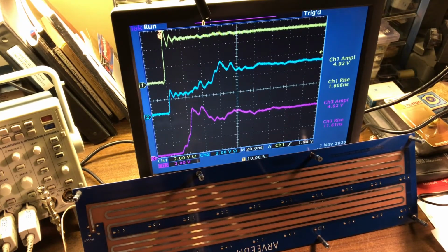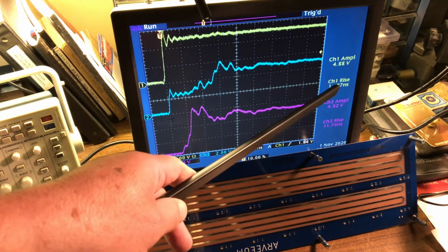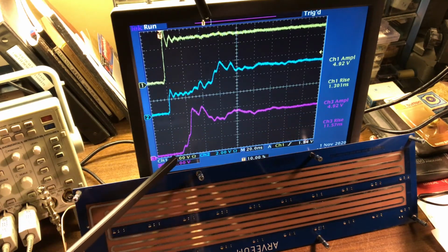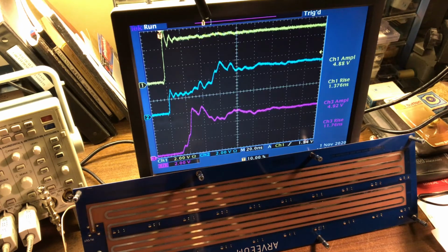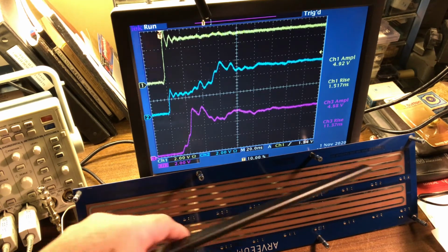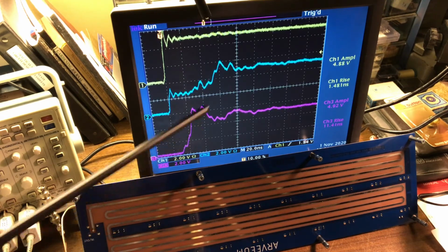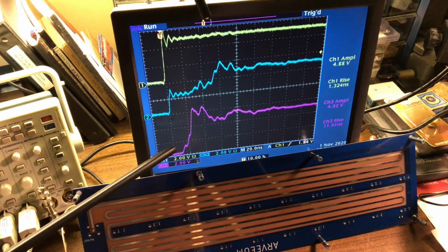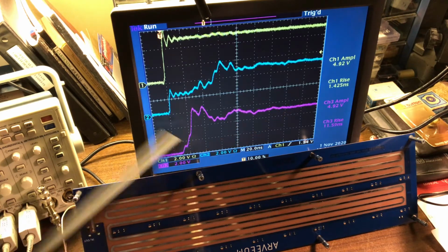current return path. So in the microstrip, and realize, as you can see in the waveform here, the switching times are really fast. Like at the input here, I'm starting at 1.5 nanoseconds, and because right now these switches are all open, the rise time has degraded, but it's still 11 nanoseconds, so it's pretty fast. So the current pretty much hugs the microstrip, and where it finds too much inductance, like in this case where there is no proper return path, then the waveform suffers and is not what it should be.